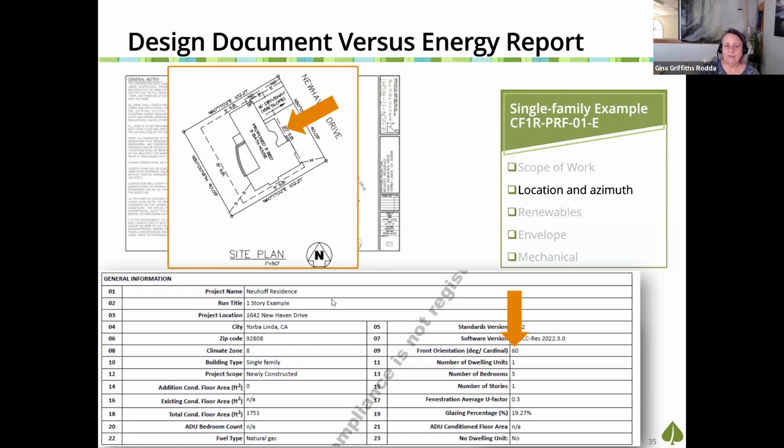Please confirm that the city and the orientation align with what your documents say. A lot of people get the orientation wrong. I always mirror it. I don't know why. It's a fallacy of mine, of which I've totally changed the energy performance of the building by not having the orientation in there correctly.